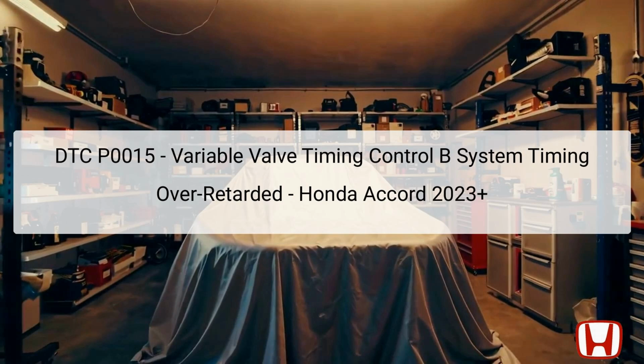Components such as the VTC Oil Control Solenoid Valve B and VTC Actuator B play significant roles in this operation. If the timing is improperly set, or if there's a malfunction in these components, it can severely affect engine performance and emissions, leading to potential drivability issues. Given the complexity of variable valve timing systems, it's vital for technicians to follow a systematic approach to diagnose and rectify this issue effectively. This presentation will guide you through troubleshooting steps for DTC P0015, ensuring that you can accurately identify and resolve the underlying problem.